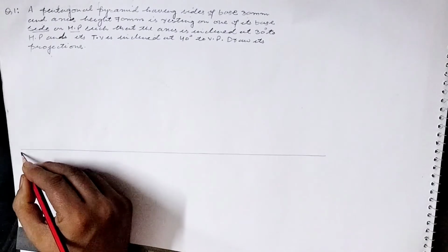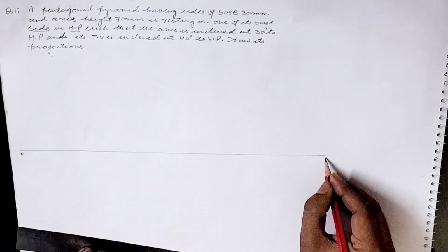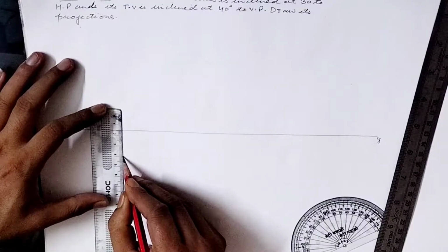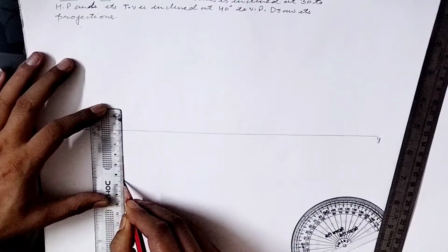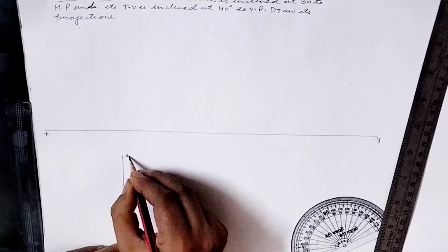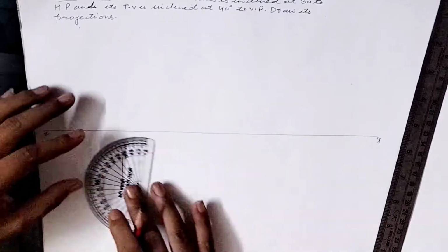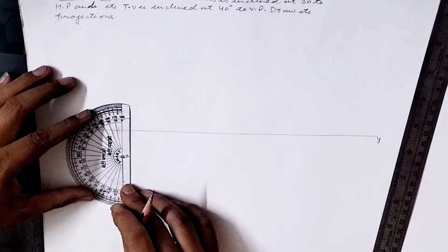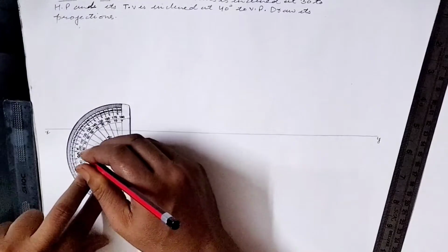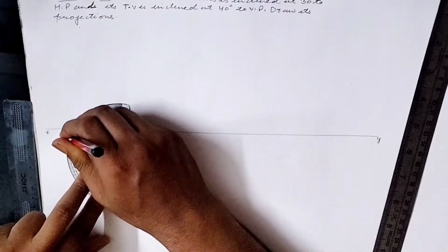So we can start the solution of our problem by placing the side of a pentagon perpendicular to the reference line and at extreme right side. Now complete a pentagon because the problem is based on a pentagonal pyramid. So its top view is as a pentagonal pyramid.